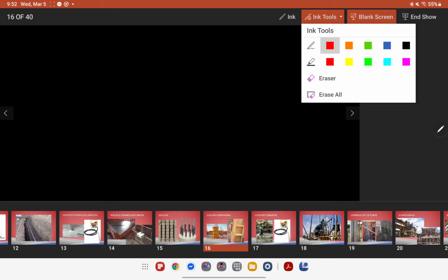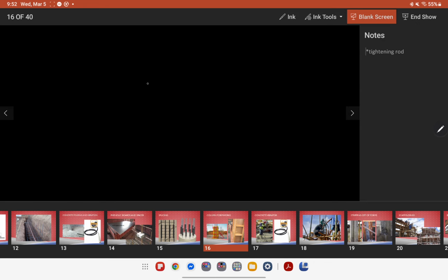Okay, it will look something like this. So if this is the size of your column, you'll have to provide a plywood here. This will be the plywood, and this will be another plywood. And then you will provide a vertical stud here and also another vertical stud here. Hold on, I need to redo this.